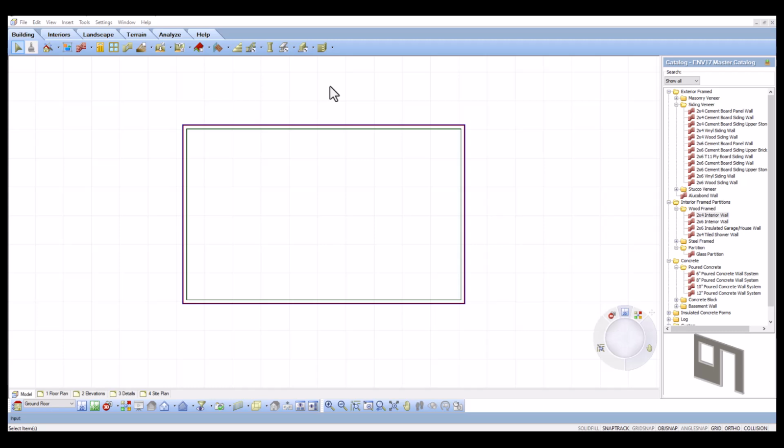In a design that calls for parallel gable roofs, we need to create two separate roofs that will sit side by side. However, Envisioneer will always try and merge roof edges that overlap, so we must make sure that they do not overlap. In the example we are using, a 40-foot by 25-foot rectangular structure has been created. We will add our parallel gables to this structure.